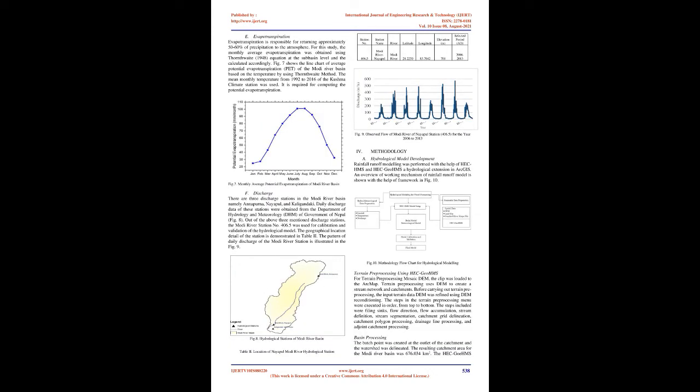15 used HEC-RAS, Hydrologic Engineering Center's River Analysis System, for comprehensive hazard mapping and risk assessments in the downstream region of the Karnali River Basin for different return period floods. In Nepal, based on HEC-RAS and its ArcGIS extension, HEC-GeoRAS, previous studies have mapped the flood hazard in the Bishnumati and Baka rivers of Kathmandu. 16, 17 used HEC-RAS, HEC-GeoRAS, and ArcGIS for the preparation of 1D floodplain maps and the WECS/DHM method to analyze the flood frequency in different return periods.